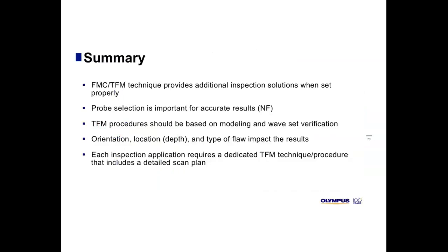So let's summarize. The FMC TFM technique provides for sure additional inspection solutions when set properly. The probe selection is very important for accurate results. The TFM and the FMC TFM obey exactly the same rules of physics as phased array and conventional UT. So the near field notion is still very important. We cannot focus beyond the near field.